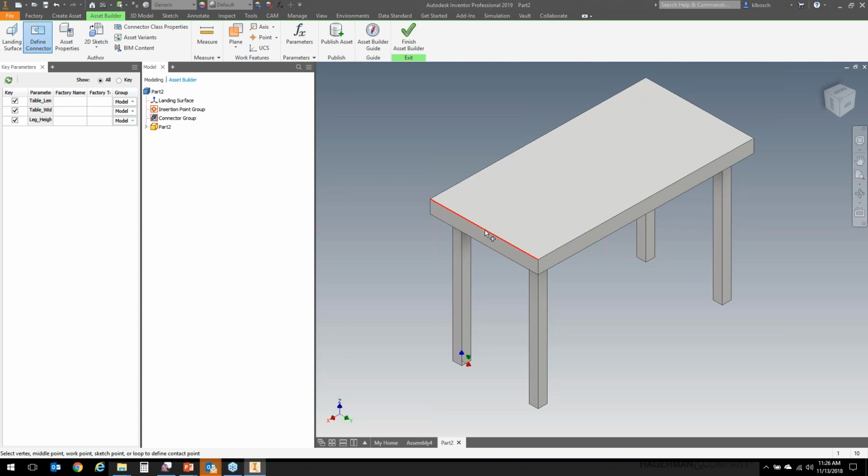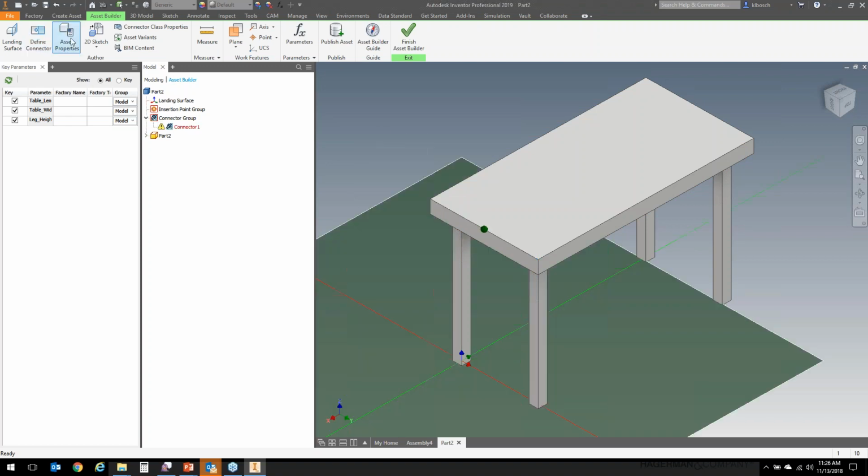You can grab just a middle location, and once again, you want to pay attention to the X direction, and more so in this case, notice the Z direction. So I'm going to highlight that and set that so that my Z direction is in the upright location. And we'll click OK on that.